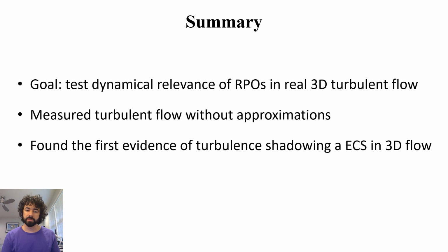To summarize, the aim of this research was to establish the dynamical relevance of exact coherent structures in real 3D turbulent flows. We did this by working in the Taylor-Couette geometry, which allowed us to make measurements without approximation that we could compare to the real 3D flow. By doing this, we found the first experimental evidence for the dynamical relevance of exact coherent structures in real 3D flows.